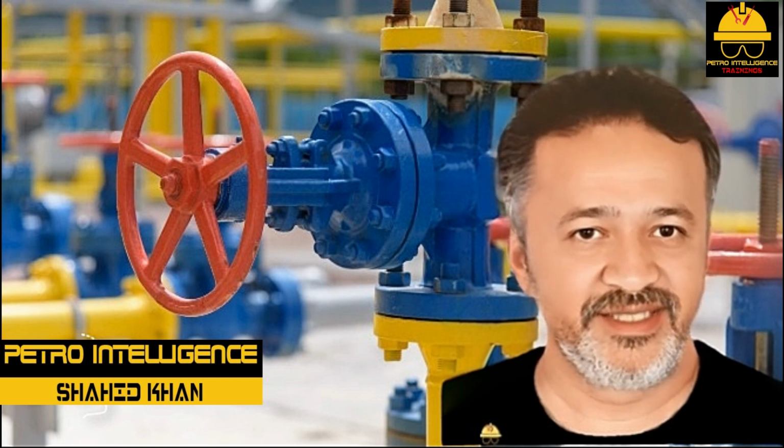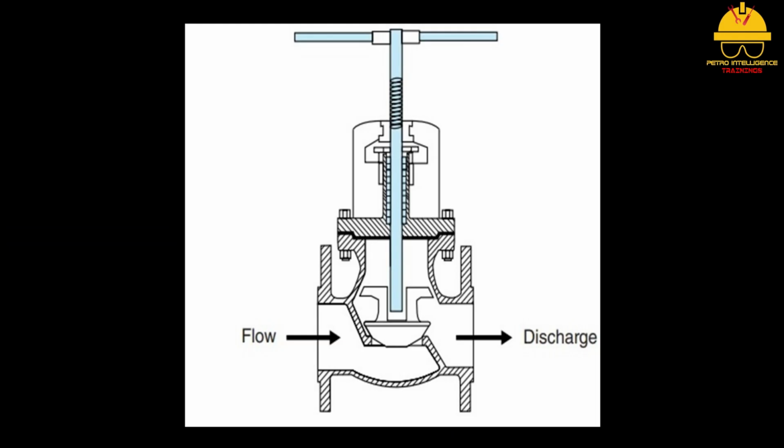A fourth design is the stop check design, which has characteristics of a lift check and a globe valve as shown in picture. In the closed position, the stop check disc is firmly seated. In the open position, the stem rises out of the body of the flow control element and acts as a guide for the disc. In the open position, the stop check functions like a lift check with one exception. The degree of lift can be controlled.